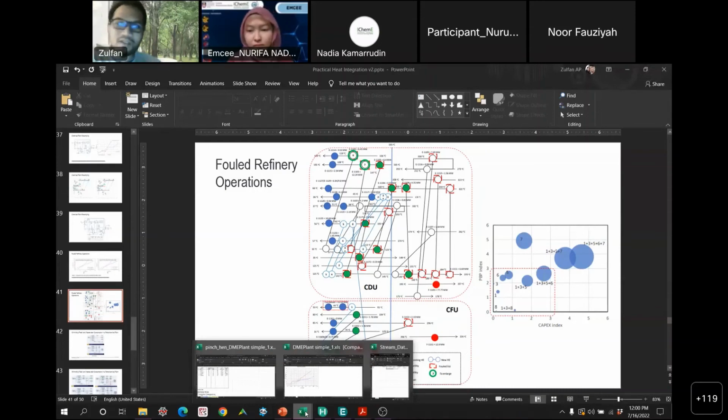There are some estimations on that. You can calculate that basically 1 over U equals 1 over h something, but those are all empirical equations. In practice, it is something that we have to determine ourselves. So what we did, we compared the U value from when you design this. When you design a heat exchanger, we assume a U value, and then based on the temperature profile we want, we select a type of heat exchanger, in this case a shell and tube heat exchanger, and then we can calculate the U value.